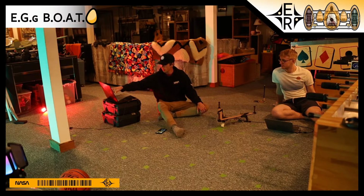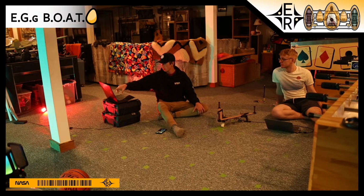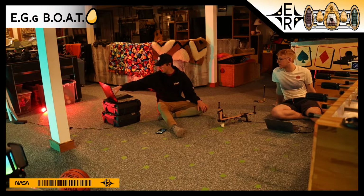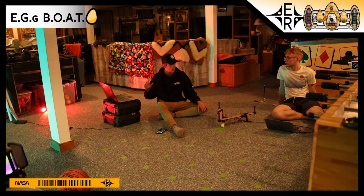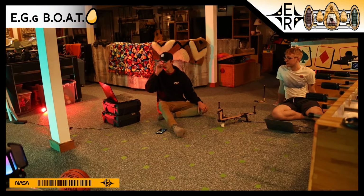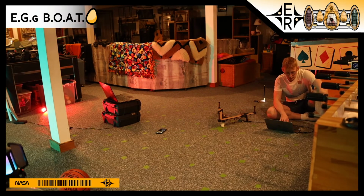I want to make an extended lip around it so that we can put one of those gaskets on for waterproofing, because I'll probably have just a screw lid on top so we can access the components. But when I screw that down, I don't want it to be plastic on plastic. I'll put a gasket in the middle for waterproofing. How do you make that? You know how you swept your antenna engraving for the antenna to slide in? Very same thing for the gasket, just a round sweep remove for the gasket line. That looks like, I'll get a part. Looks like this.